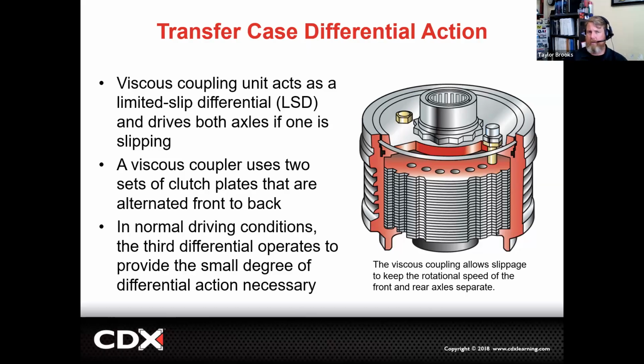There's a lot of vehicles that do have these viscous couplings. We tend to see them in more automotive applications, not truck applications or SUV applications, but we do see viscous couplers quite a bit. The key note with these is they are not serviceable. They're not rebuildable. Usually, when they do go out, there's nothing internal that can be salvaged. That's why they're all replaced as a unit.